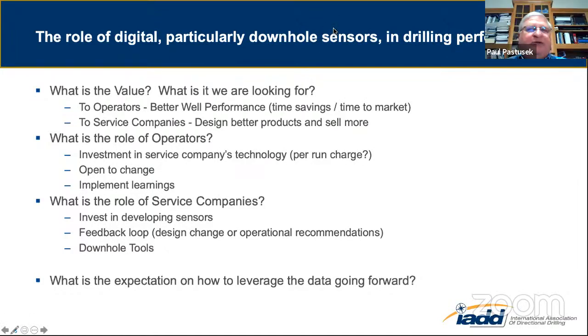I think the data that you get from a downhole module adds dramatically to the quality or the effectiveness of those trials. So, you had a bad run. Would you find out that, oh man, I drilled out on site, in the shoe and this thing was rattling around like crazy, and you go, the bad run had nothing to do with the trial that I planned? Or vice versa, you see that you just did a new bit design that is inherently more stable in that little zone that I was looking at, the difficult to drill section or whatever. So I think the downhole tools can improve the effectiveness of each design cycle tremendously.